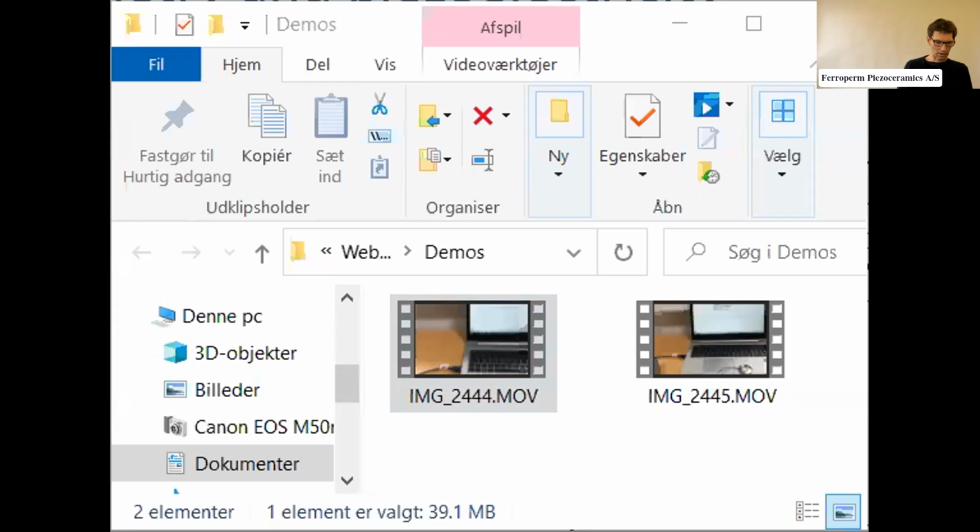So I think I'll start the video from the start. What I've used here is the little piezoelectric loudspeaker that I showed you before in the second example. I'd like to show that if you hit it, if you apply some mechanical stress, there will be an electrical signal. And this I do by just connecting a very cheap oscilloscope to this piezoelectric component, and then you'll see a voltage signal on the oscilloscope. So let's see if it works.